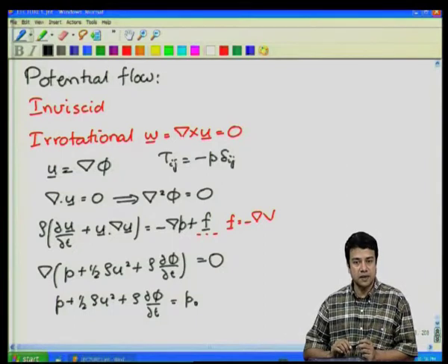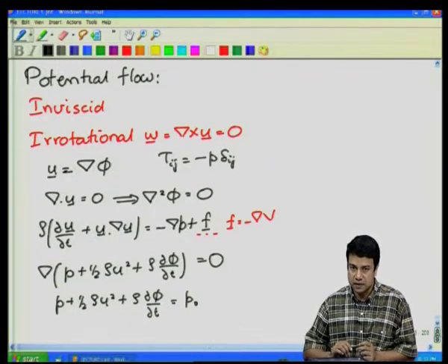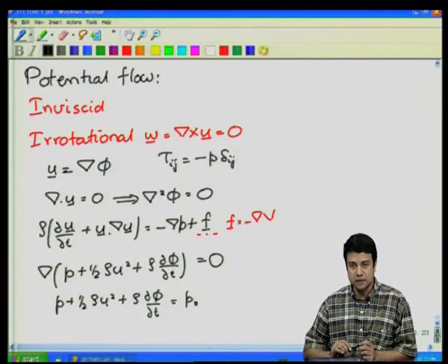The reason is because we have neglected viscous dissipation in the potential flow equations, and therefore, there is no change in energy. The energy is not dissipated by viscosity, energy is conserved. If energy is conserved at constant velocity, there is no need to put in energy in order to keep the object in a state of motion, and therefore, you need no net force in order to move the object at a constant velocity. When the object is accelerating, of course, you do need a net force, and that force is equal to the added mass times the acceleration.